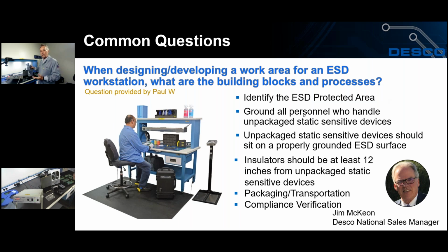So the importance of static shielding bags is that if my device isn't on a grounded workstation or an ESD controlled area, I need to keep my components, circuit boards, etc., in a closed shielded container when I'm transporting those devices.